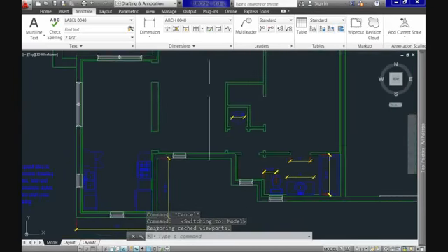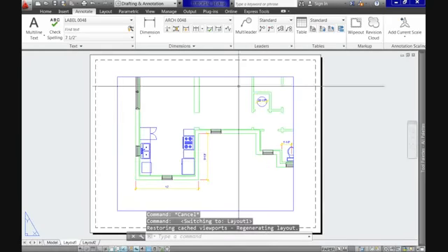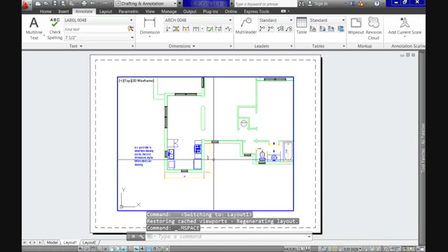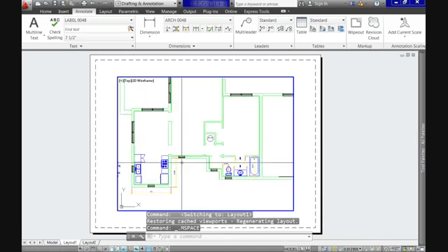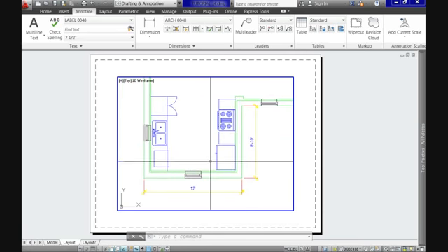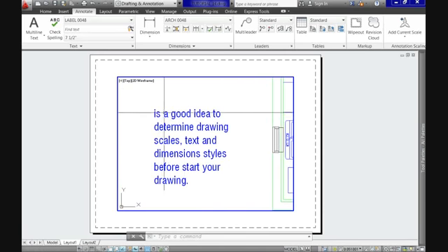As we all should know, we draw in model space where objects are typically drawn at actual scale. But then we have to print or plot those drawings, and either we reduce or increase the size to fit the paper in which they are presented for production or construction purposes. The main issue is that although we have to scale our drawing, the annotations on it, like text and dimensions, should be kept at a fixed size on the paper space, or on the paper, for consistency.